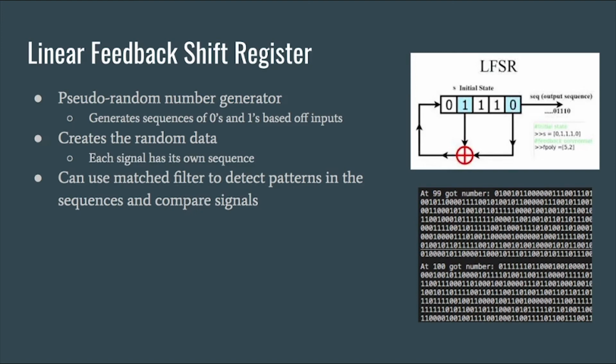And since these bit sequences vary on the input, each signal has its own sequence attributed to it. This is important because then we can use a matched filter to search for bit patterns in these sequences and help us determine the signals.